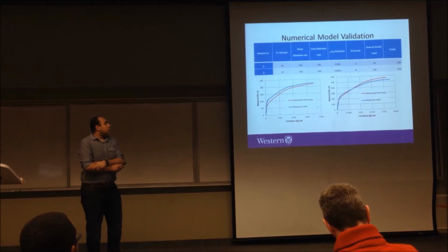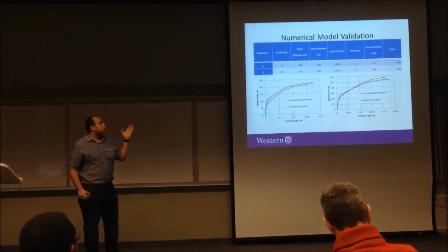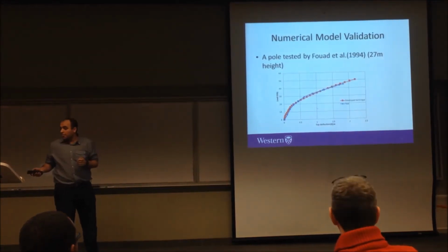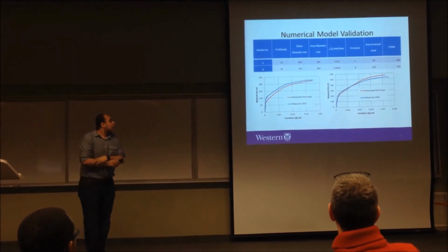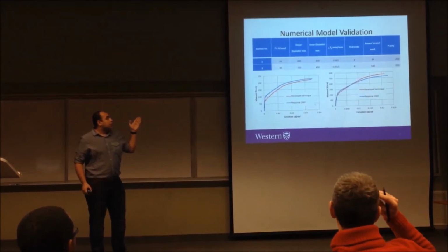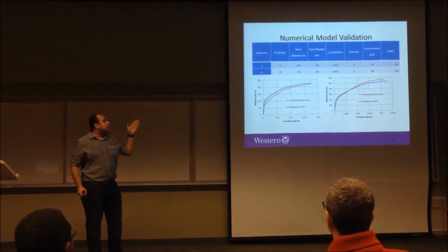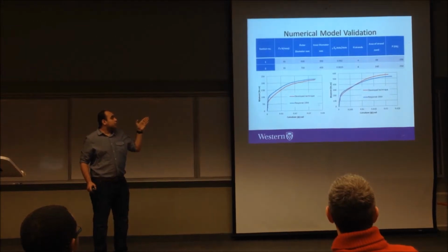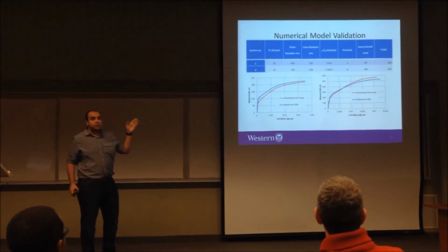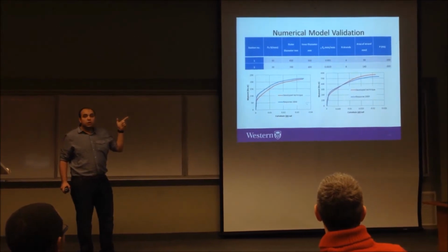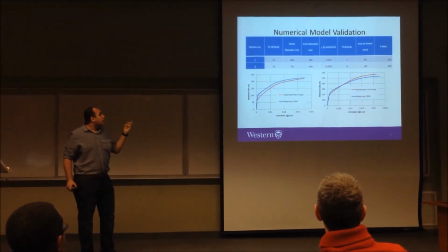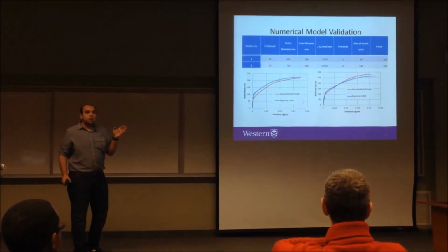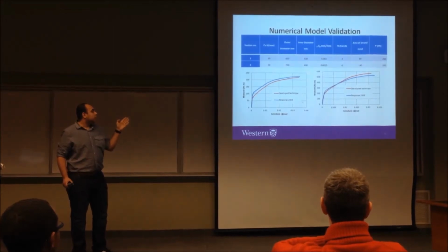For the validation of the numerical model, two pre-stressed hollow circular cross-sections are used. Various outer diameters, various inner diameters, various initial straining of the strands, and different numbers of strands, 4 and 8, are tried, along with different areas of strands and different compression forces acting on the cross sections. The moment curvature diagram is compared with the Response 2000 program, and it shows a great agreement for the